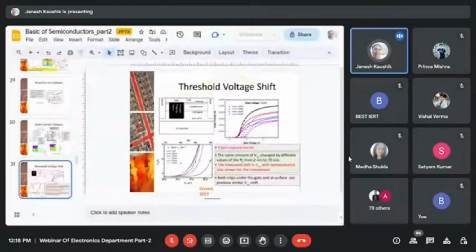If you talk about the dimensions, the AlGaN barrier thickness is around 22 nanometers, and there is a GaN buffer of micron thickness, but the main channel is around 100 to 200 nanometers. We try to remove each and every trap from that location, because any trap present there will reduce the reliability and deteriorate the performance drastically.